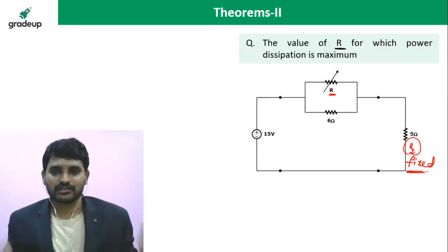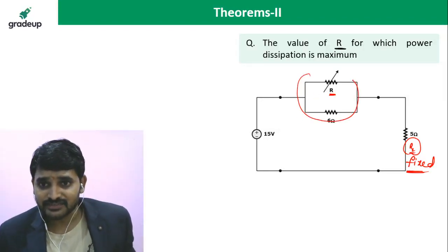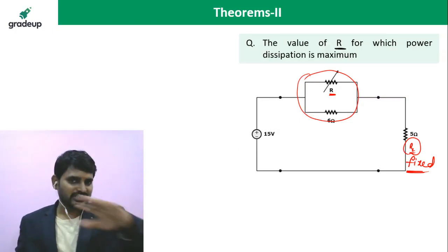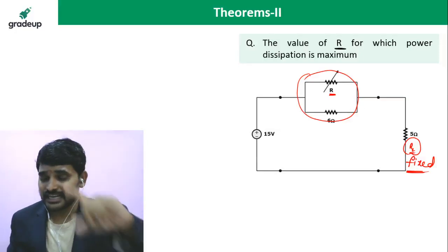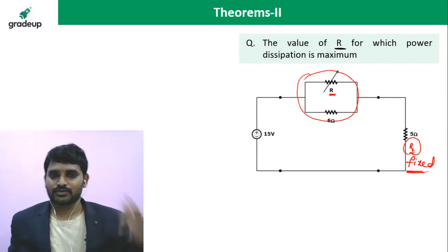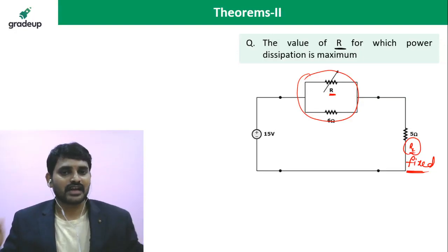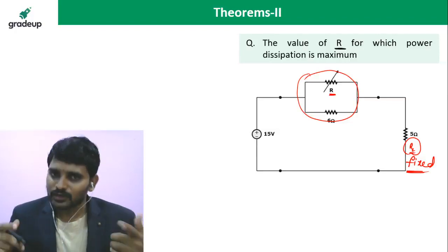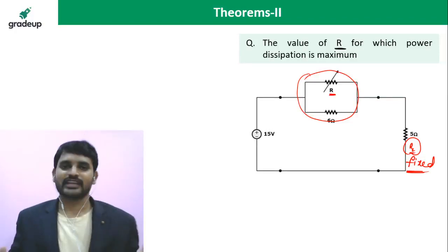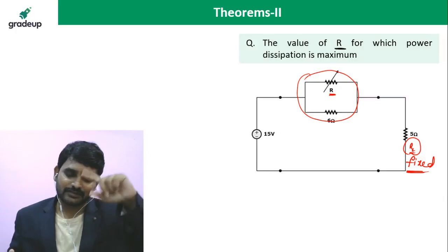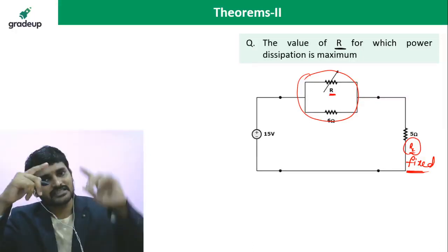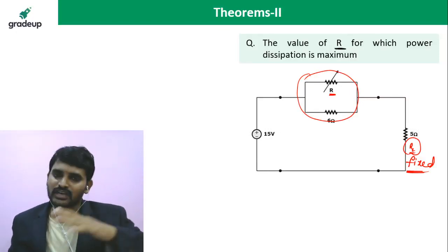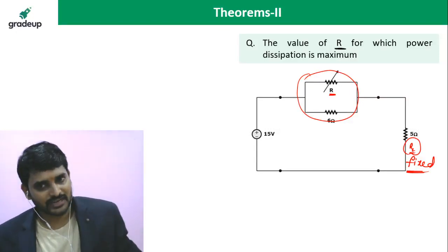Alright, the same logic here also. Whatever the medium which is connected between source and sink should have minimum resistance. You might be aware of this question, but try to think in the practical format. Take a transformer and your house. If your home is suffering from low voltage, what do you have to do? Will you do anything at your circuit breaker? You cannot do anything. Go to the transformer and change the tap changer. Increase the tap changer, increase the voltage level, then you will get sufficient voltage and you can have good power consumption. That is what I'm trying to say.